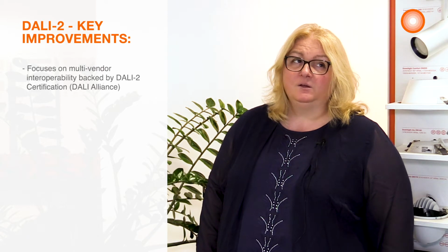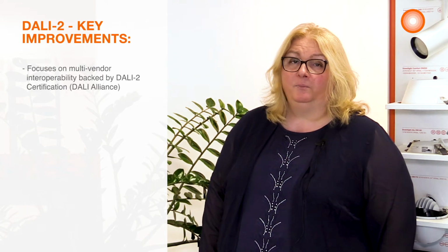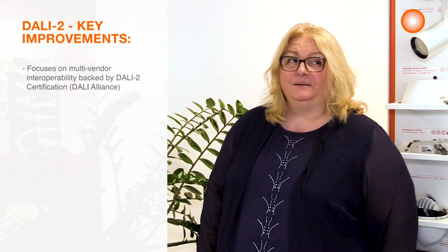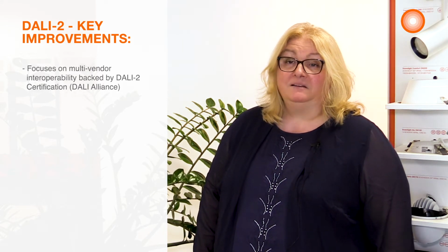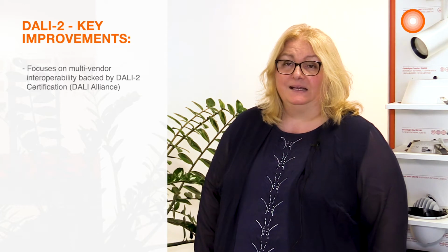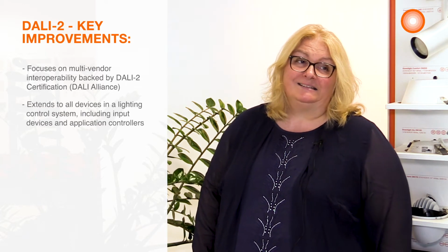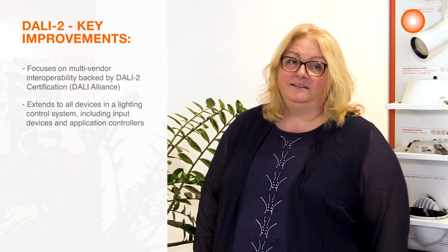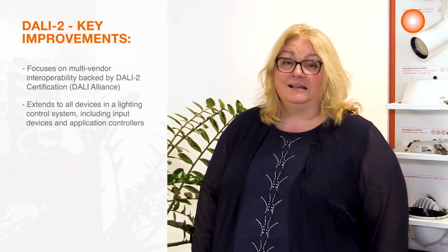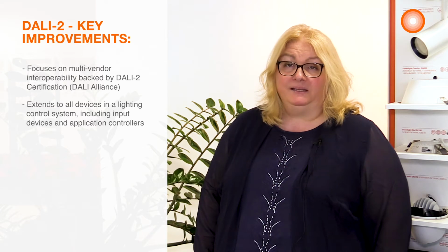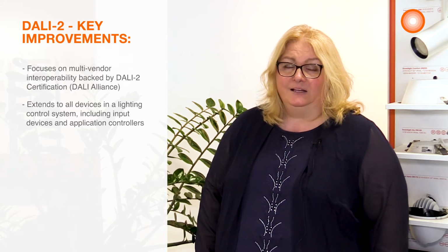What are the key improvements of DALI 2? It focuses on multi-vendor interoperability, backed by DALI 2 certification, which is done by the DALI Alliance. It extends to all devices in a lighting control system, including input devices such as sensors and application controllers.